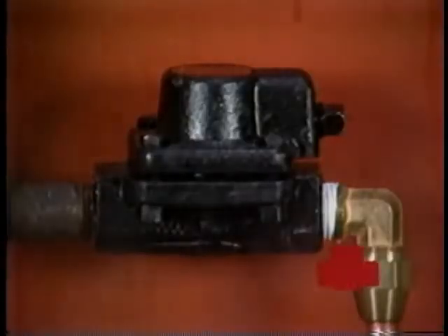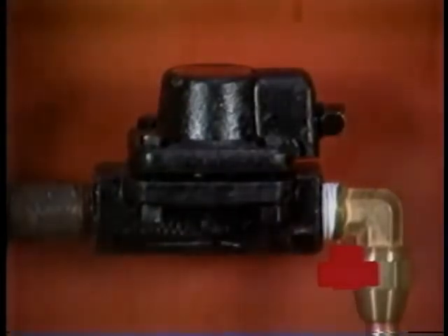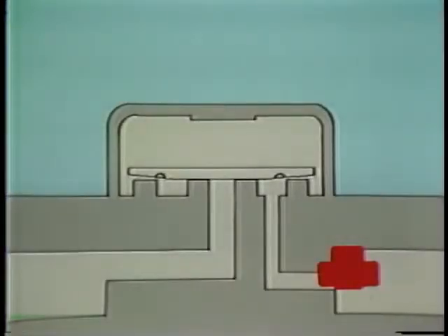The disc trap is not recommended in situations where the average load is less than 3% of the trap's rated capacity. Live steam causes the trap to cycle frequently, prematurely wearing the seating surfaces.